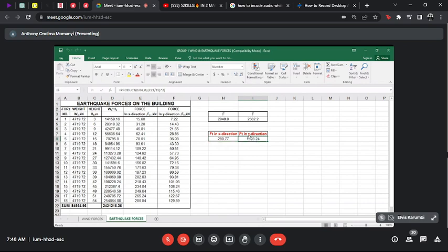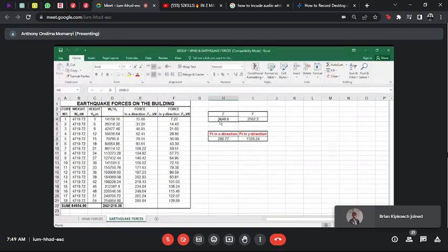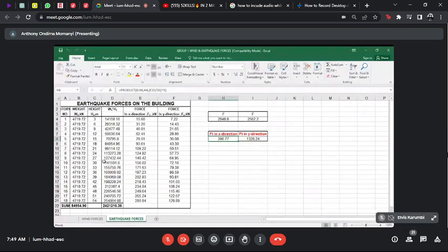There they had a formula, if you click on that cell, we inputted that formula: 0.04 multiplied by H4, which you can see is the total force, this one here, and then multiplied by C21, which was the sum of this column D, divided by the dimension in that direction which we are considering.